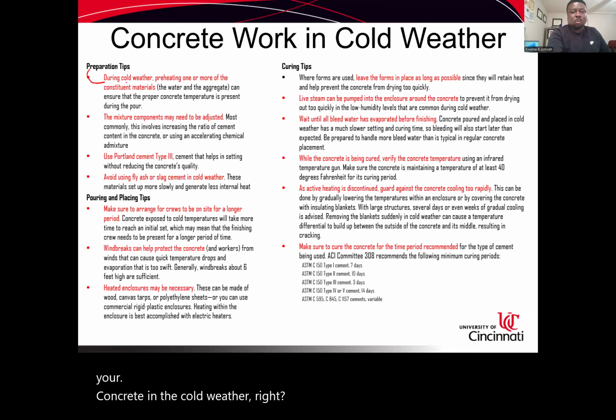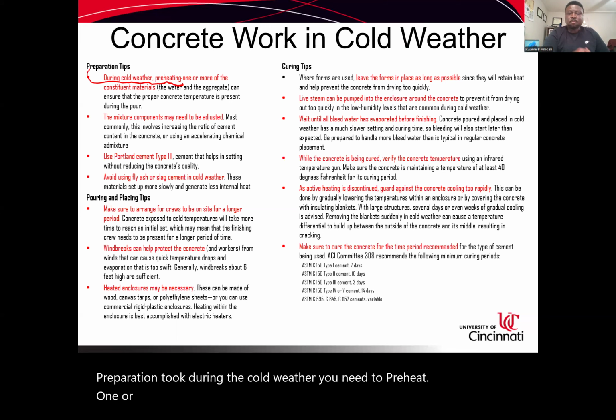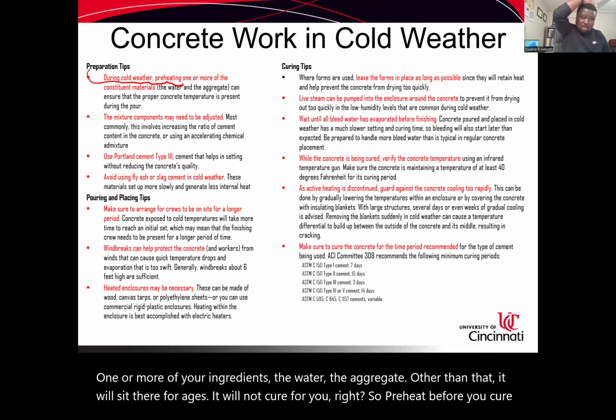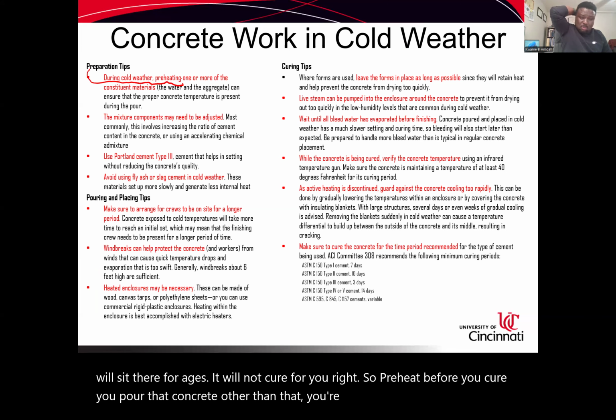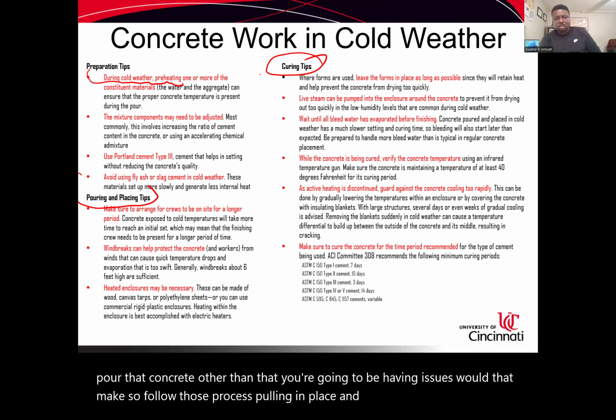In preparation for cold weather, you need to preheat one or more of your ingredients, the water, the aggregate. Other than that, it will sit there for ages. It will not cure for you, right? So preheat before you pour that concrete. Other than that, you're going to be having issues with the mix. So follow those processes, pouring in place, and then curing tips and so on.